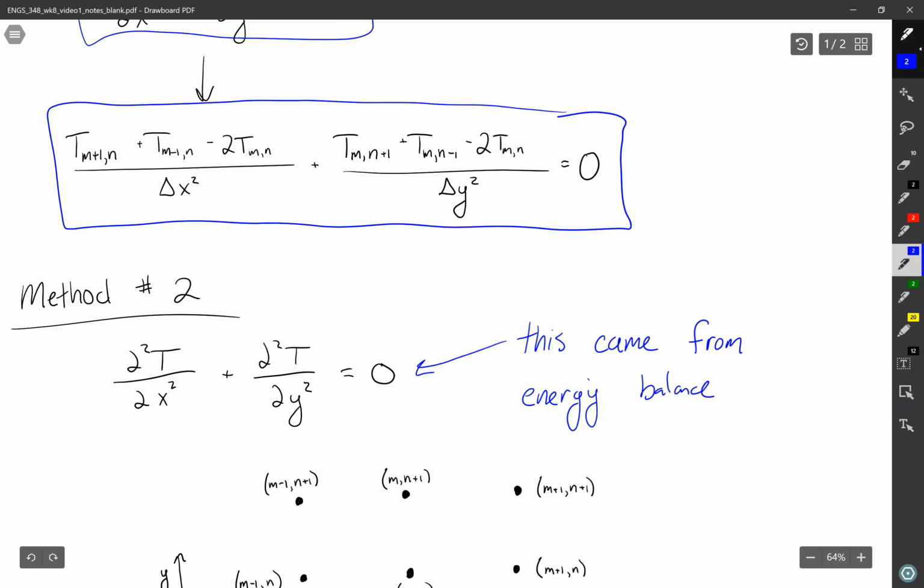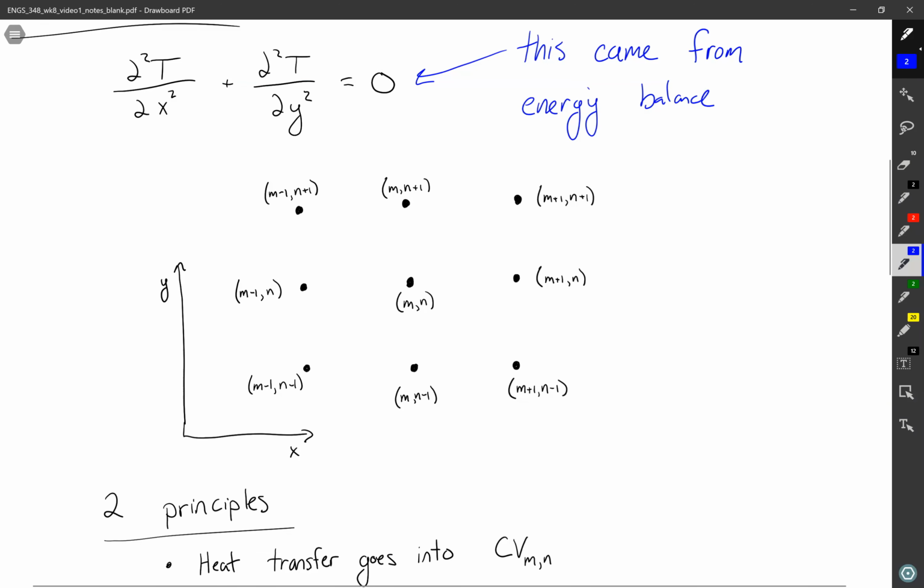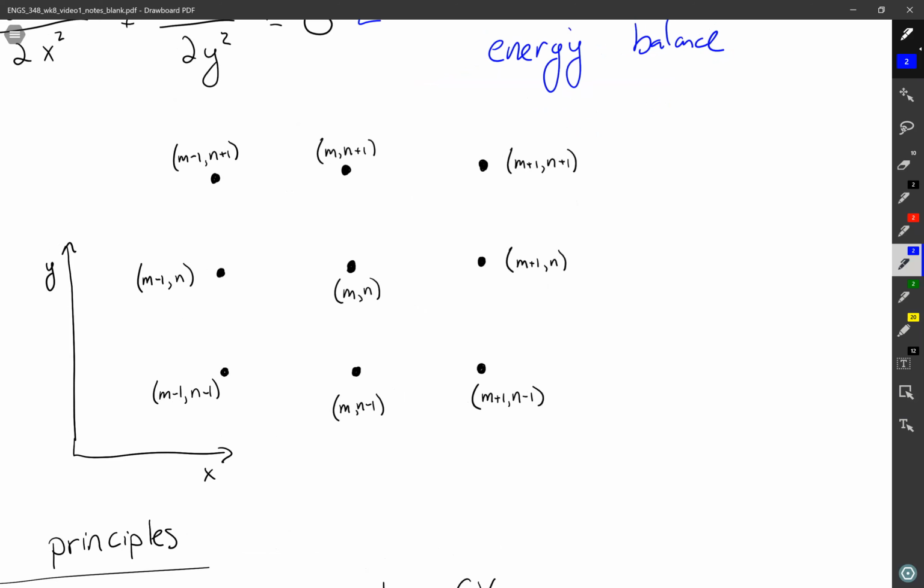So we're going to see how we can build up the same understanding by, instead of solving the equation numerically, looking at the discretized problem, right? The problem where we've diced everything up into little boxes, and then doing energy balances for that problem. So we're going to choose a grid like this. These are our discretized points. What we're trying to do is not find the temperature everywhere, but find the temperature at these individual points. These are just 9 points in our object.